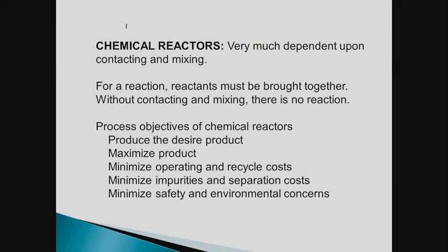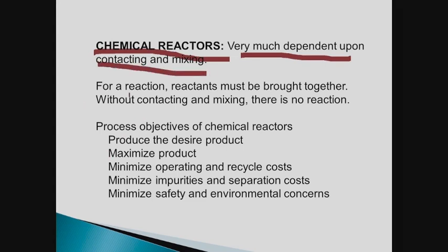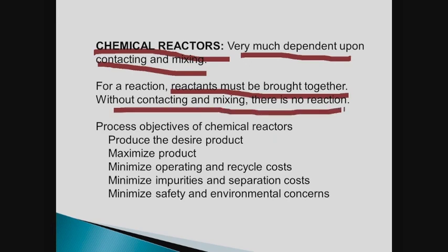Chemical reactors are very much dependent upon contacting and mixing. Right? Reactants must be brought together. Without contacting and mixing, there is no reaction. So your objective is to produce the desired product, maximize the product, minimize operating and recycle costs, minimize impurities and separation costs, and minimize safety and environmental concerns.